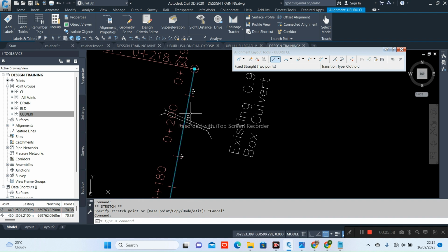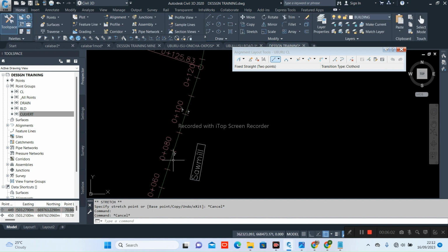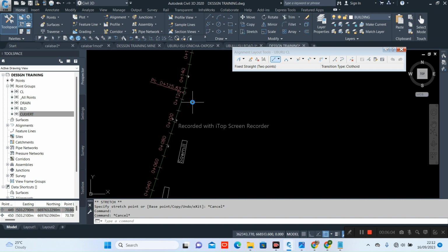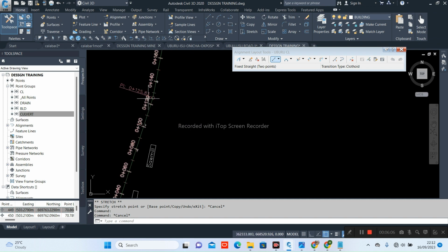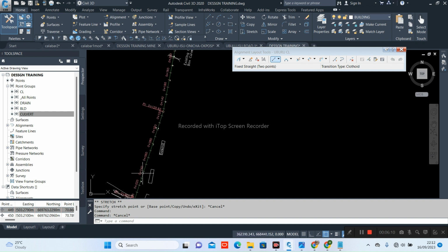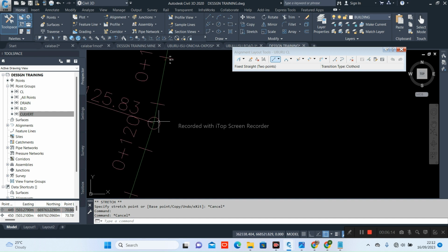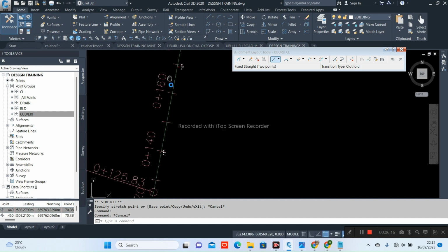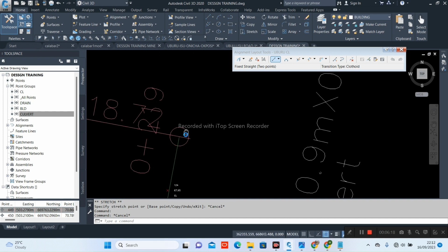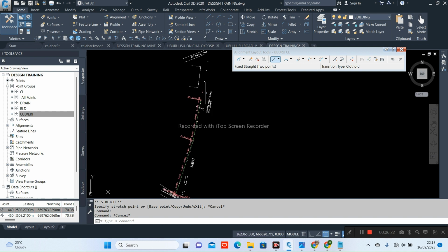So you can see it has practically aligned itself. So now we've done, we have our point of intersection. What next? We have our curve. We have our straight. You can't have a road where the car will drive towards here, then there'll be a sharp change in direction again, then it gets somewhere here. The same thing happens. That's why we need to have a curve on it.